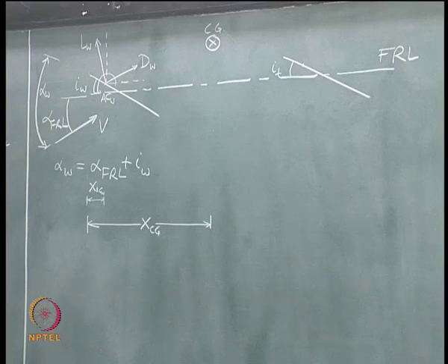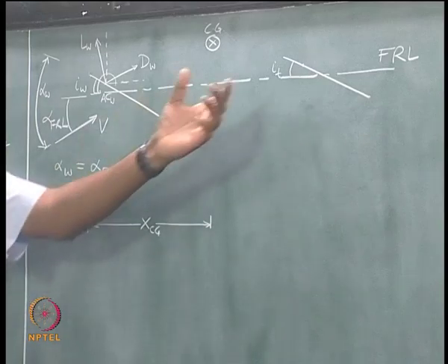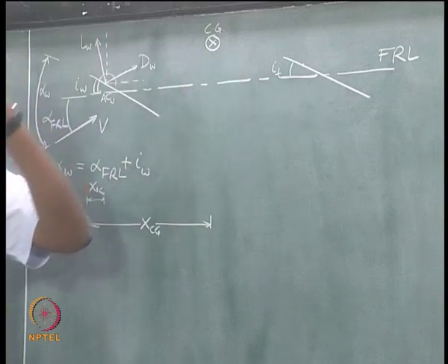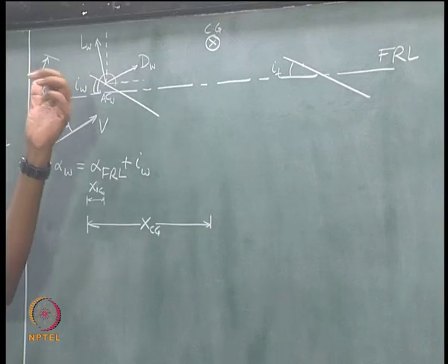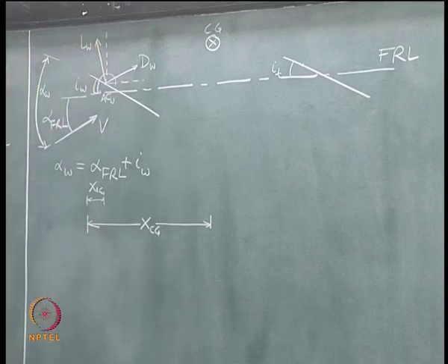All right. So, this part actually we have covered in the last lecture. We are going to focus on the tail now. I just said, because of the tail location which is in the wake of the wing, right, we have to account for what is called the downwash angle, right, and that is because of the tip and the leading edge trailing edge vortices at the wing, right.